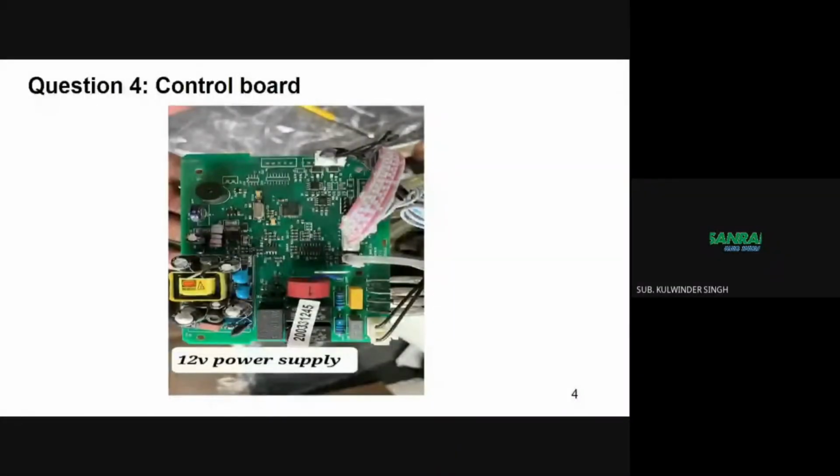Thanks, Mavi. So the problem with the machine is that it is not powering on, so we will start from the power socket, checking the voltage availability with the multimeter. If available, now check the power cable either by the continuity check with the multimeter, or voltage check at the point where the power lead enters the machine.